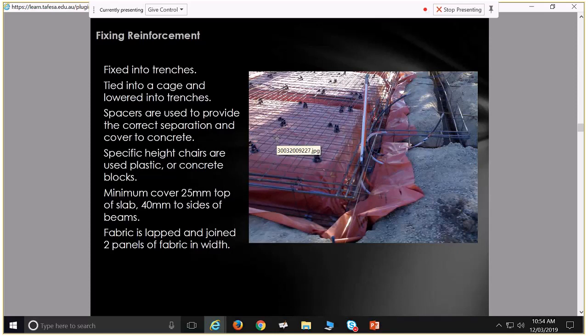So obviously, in order for that to work effectively, the soil needs to be at the exact height. Yeah, it needs to be. So how do you check that? Well, you can check that with a laser level. Okay. Whose responsibility is that normally? That's the people working on this. You have contractors for doing the site works. It's their responsibility.